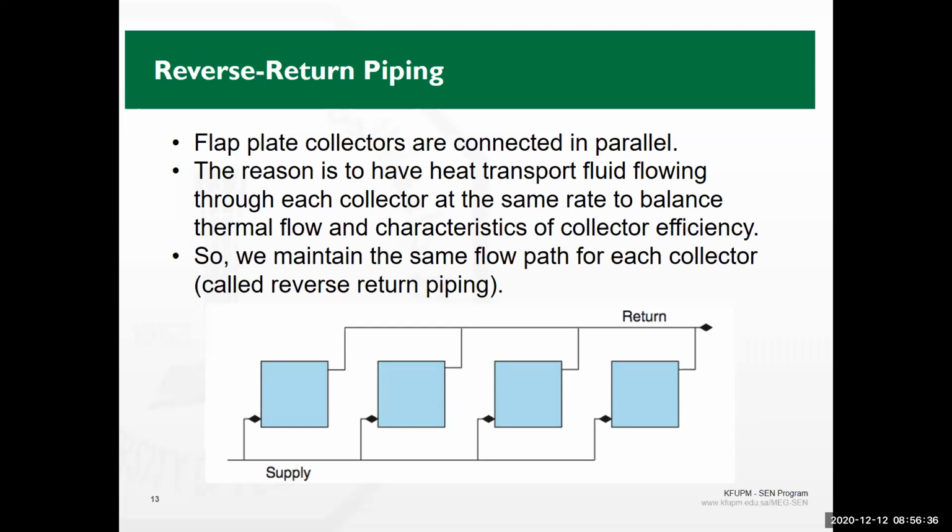What we see here is some sort of symmetric kind of connections across the flat plates. Look at the supply, look at the return, you'll find that they are symmetric, the same length of pipes, and this is actually meant as a good design for the unit, so that you can have some sort of balanced operation of the unit. You don't have very long tubes on one side and short tubes on the other side, so it goes out of balance in terms of the amount of energy which is carried by the water as it passes through the tubes, in or out.